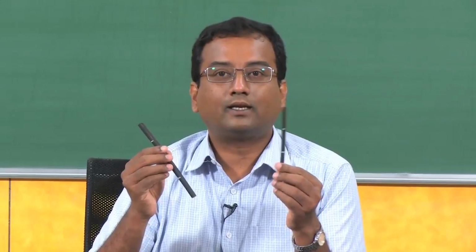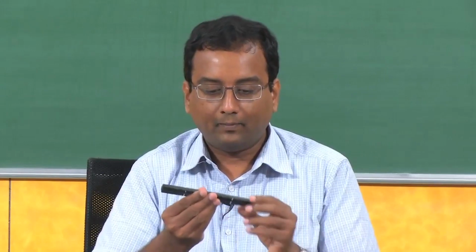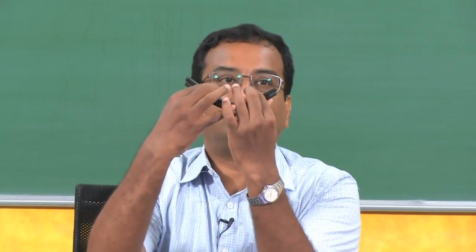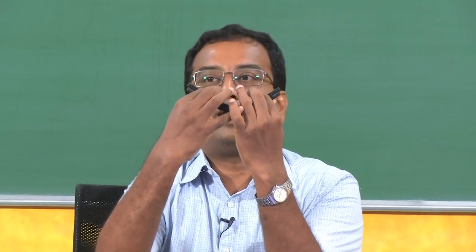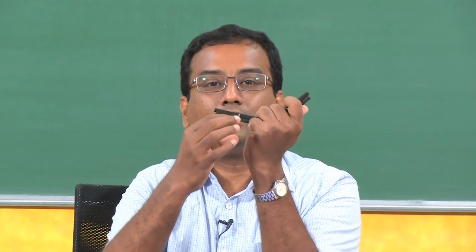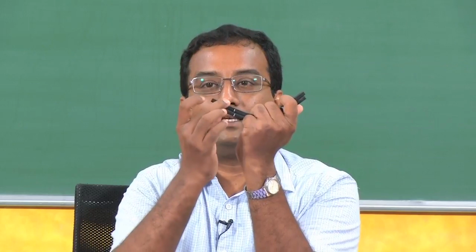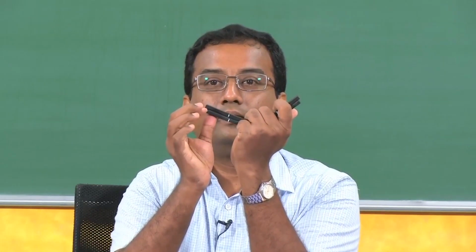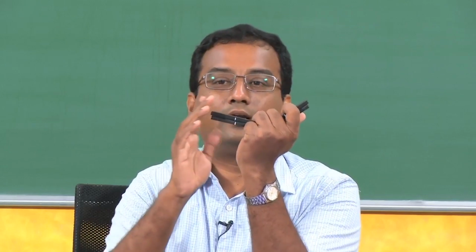So, now to understand why the sigma xy arises, let us look at a small demonstration. I have these two rubber blocks which are not connected to each other. Now, let me say I bend it by applying a non-uniform load. See what happens at the edges. The edges are not flat, the plane sections are not remaining plane. There is a shift in the white line, and you can see that at this edge there is a zigzag nature of the plane there. The plane is not remaining smooth.